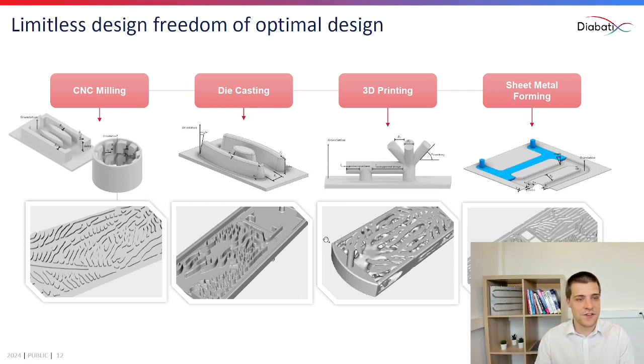As a bonus feature, ColdStream will take manufacturability into account from the start. So depending on how your design will be manufactured, you can fine-tune those settings to make sure that whatever ColdStream outputs will meet your manufacturing constraints. So for battery cold plates, sheet metal forming is by far the most popular option, where I can specify, for example, minimal and maximal channel width.